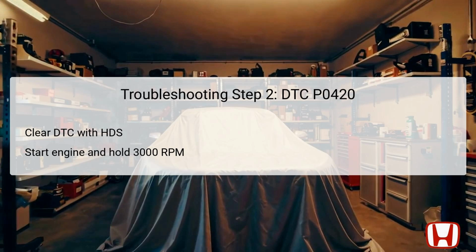This step needs to be maintained until the radiator fan activates. Then, allow the vehicle to idle. Such actions help to reset system parameters, giving the catalytic converter an opportunity to function under normal operating conditions. This strategy may also provide more accurate readings on subsequent tests.